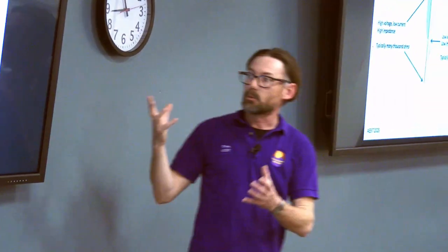So when we take those measurements, we measure our current at a given spot, we measure our voltage at a given spot. The ratio of those, voltage divided by current, that's our impedance. And impedance will become very important when we're feeding an antenna.